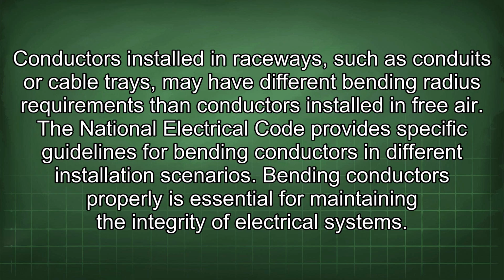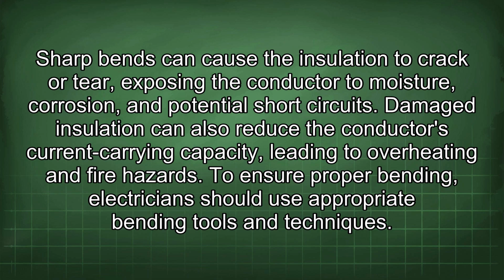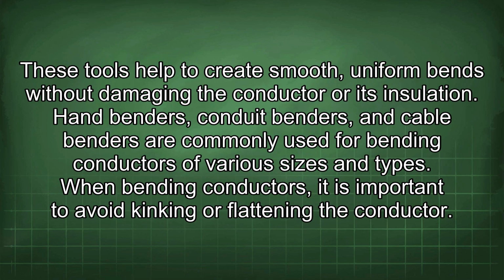Bending conductors properly is essential for maintaining the integrity of electrical systems. Sharp bends can cause the insulation to crack or tear, exposing the conductor to moisture, corrosion, and potential short circuits. Damaged insulation can also reduce the conductor's current carrying capacity, leading to overheating and fire hazards. To ensure proper bending, electricians should use appropriate bending tools and techniques. These tools help to create smooth, uniform bends without damaging the conductor or its insulation.